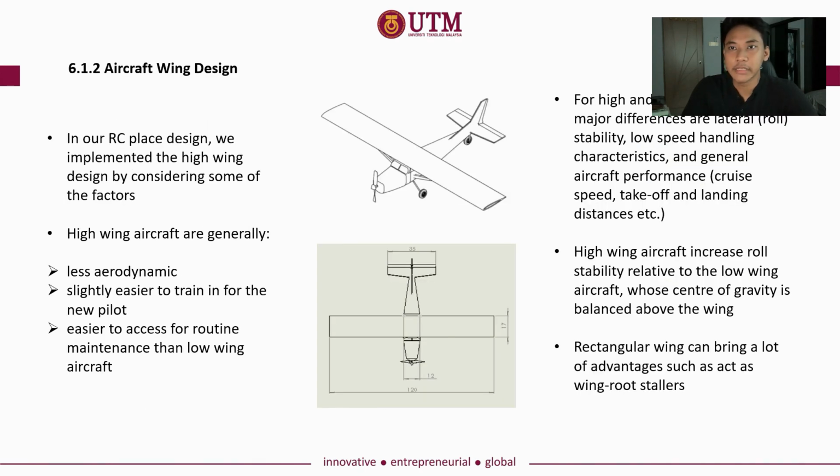Okay, we move to the next one, which is aircraft wing design. In our aircraft design, we chose to create a high wing configuration. We implemented the high wing design by considering some factors: high wing aircraft are generally less aerodynamic, slightly easier to train in for new pilots, and also easier to access for routine maintenance compared to low wing aircraft.